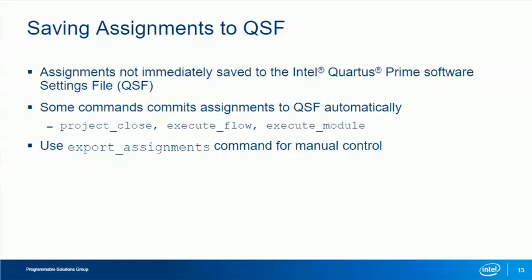It's important to be aware of how the Intel Quartus Prime software processes assignments. When you make an assignment in Tcl or in the GUI, the assignment is not immediately saved to the Intel Quartus Prime software settings file, or QSF file. Because of this, it's possible for settings to get out of sync if you have the project open in multiple places or if you're editing the QSF in a text editor.